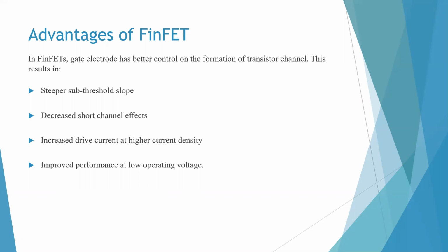Basically in a 3D FinFET structure, the gate electrode has better electrostatic control of the transistor channel formed, and this results in a steeper subthreshold slope of transistors, resulting in a reduction of short channel effects like subthreshold voltage, drain-induced barrier lowering, and all the others. And also it increases drive current at higher current density and improves performance at low operating voltage.